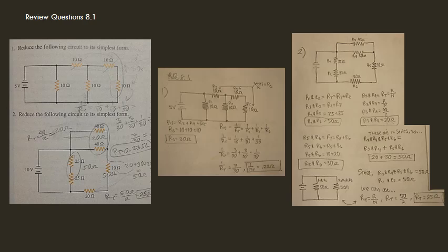So we end up with the circuit that's drawn on the lower right of your screen, number 2. That circuit is the simplified version. So we have 2 resistors of 50 ohms each in parallel, and we can use the division formula again, where R total equals R over N, N meaning the number of resistors that are the same value. So 50 divided by 2, we have 25 ohms of resistance for the circuit total. Total resistance in the circuit.